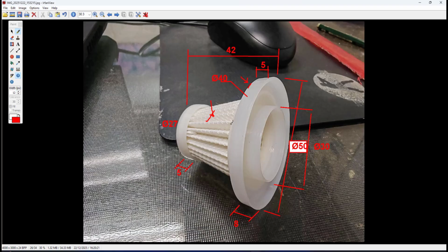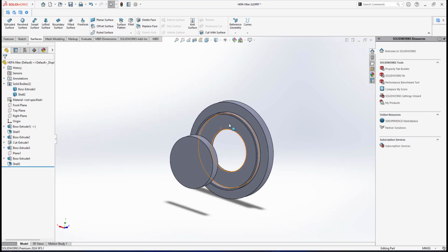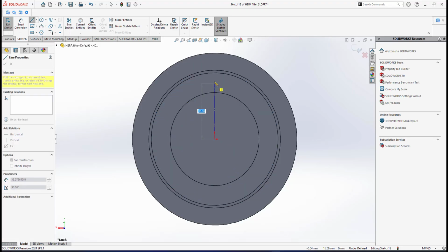The material is a microfiber material, and the shape is actually a star shape, so it means I will create a repeated pattern, circular pattern of a star shape. So later, and also the star shape at the front end there. So then later I will show you how I will do loft. But the best way to do this, let me show you. And here, alright, so here the base will be here. So I will select this sketch plane, and I will create a center line from this point and attach to this point.